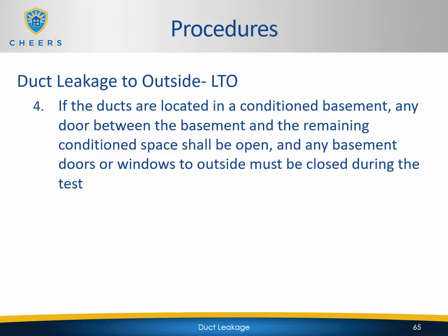If the ducts are located in a conditioned basement, any door between the basement and the remaining conditioned space shall be open, and any basement doors or windows to outside must be closed during the test.